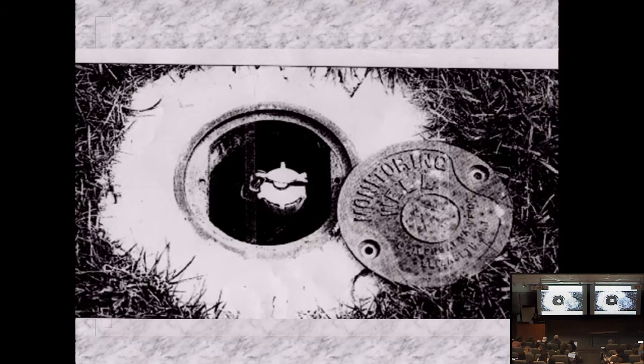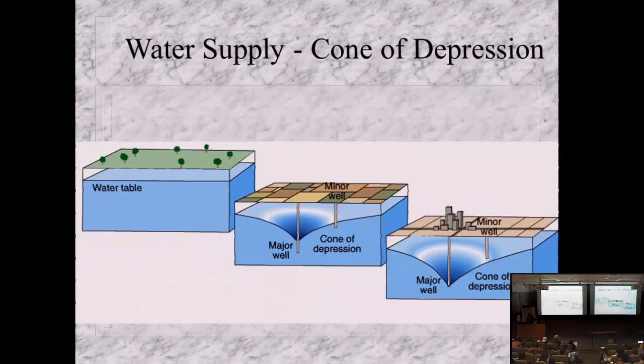They look like little manhole covers, about this big, and you have a lock and a cap on there. Then you take a water level meter, I should have brought one of these in, and you drop it down into the well, and when it beeps, you know that's where groundwater is. So it's one of the things that you do. But we try to do as few of these as possible, and then try to mathematically interpolate between the points to see what's going on.